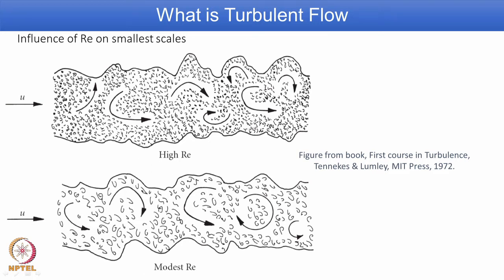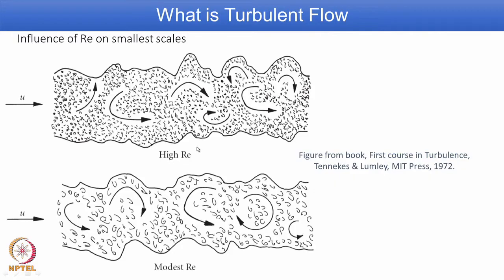And this is very important because when you model turbulent flows later, you have to know what is the smallest mesh size that you have to describe, because the smallest mesh size captures the smallest eddy size motion and the prediction becomes better. So, I repeat, as you increase the Reynolds number, the size of the smallest eddy becomes smaller and smaller, and that puts a limitation or requires careful choice of the smallest mesh size that is possible.